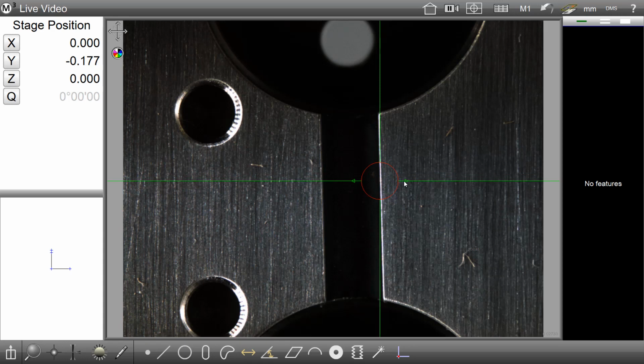The scan direction and color sense control is the same that's available in the current release of the software with the iMeasure probe. One of the other changes you'll notice is that I can freely translate this new Simple Active Crosshair in my field of view. Unlike the current M3 software, the probe will not automatically recenter to the middle of the field of view. If you'd like to do so, simply long press the Translate Rotate to recenter the probe.